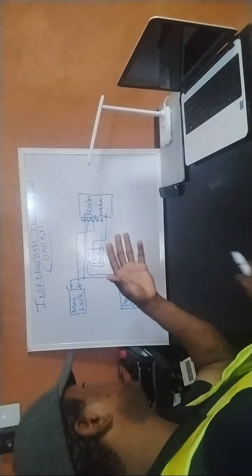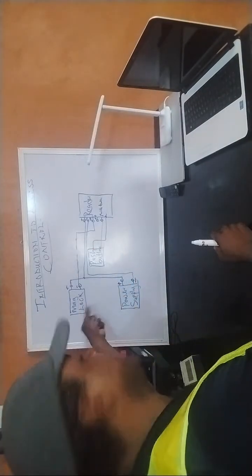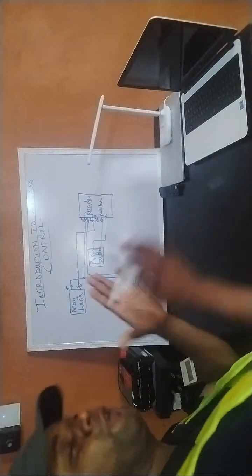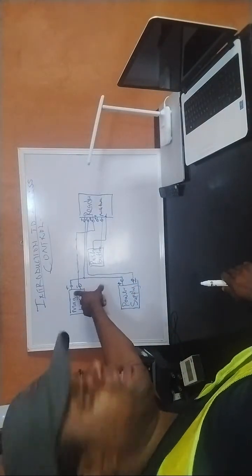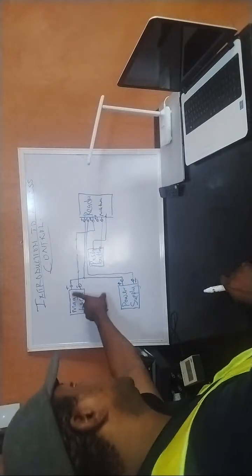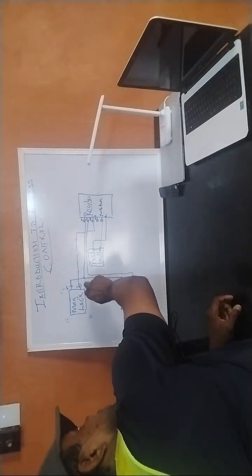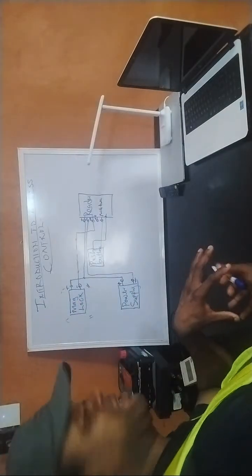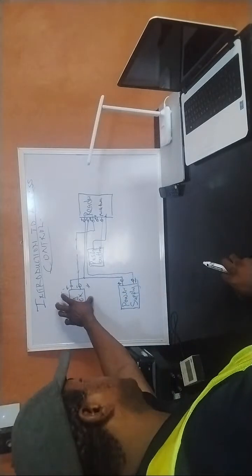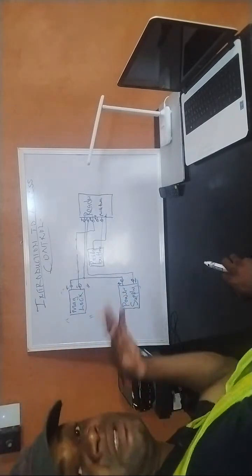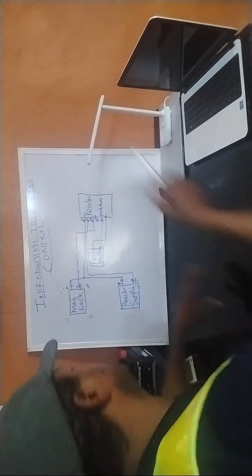Some you can set for 5 seconds. So immediately this door is open, you can have access to this place. For that time frame, let's say 5 seconds, this thing remains inactive because the inductive signal here, the coil that was active before, is now left idle. There is no supply here. So it de-energizes, it stops magnetizing. So for this time, you can just swing the door open.